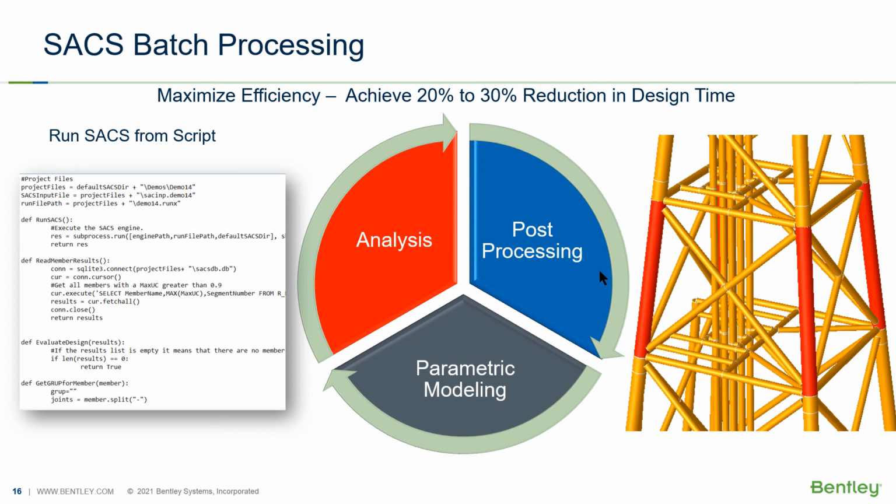So, users can perform parametric studies without opening and revising the model file for each analysis. For your reference, the SACS API is exposed in three formats: C++ library, Python extension, and COM server. All functionality is available in all formats.